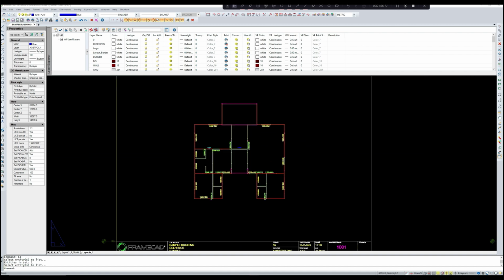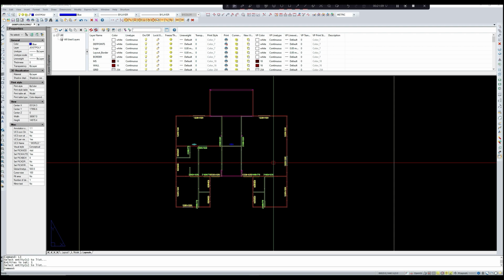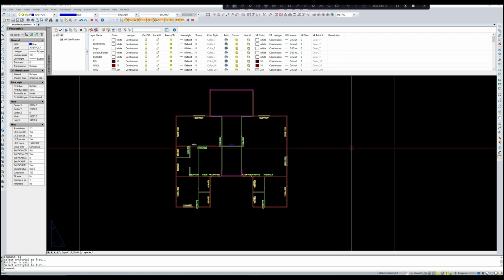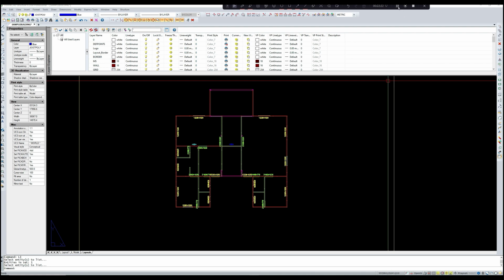Note at times the base levels don't change with collective selection as they do with individual selection. So the 3D model is showing those discrepancies. So we have to go one by one and set the base level of each wall at 3500, wherever required. Here at the first floor level, almost all of the walls have a base reduced level of 3500 mm.